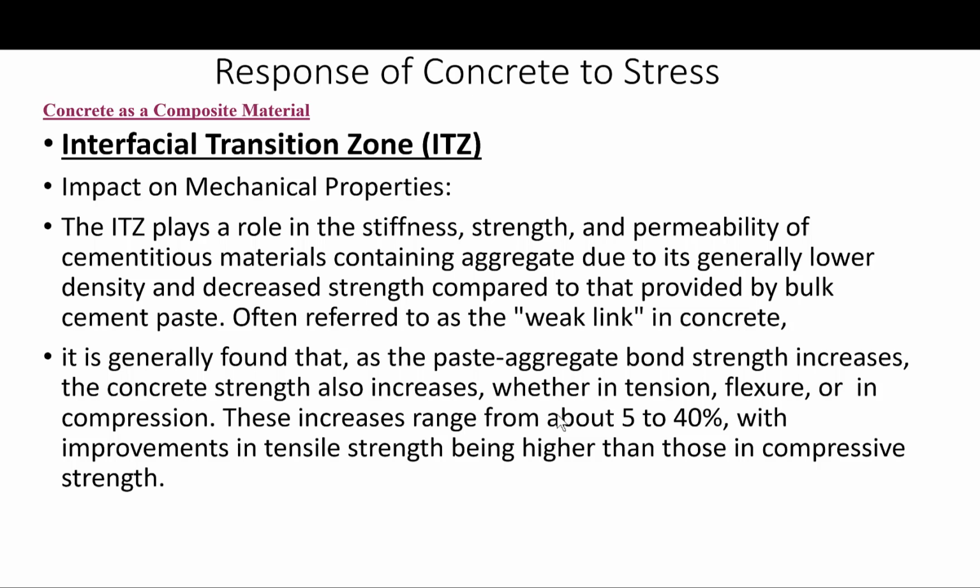So what we see are the effects of the ITZ on the mechanical properties. What are they? Currently, there are no standard test methods by which the strength of the ITZ, or more importantly, the bond strength between the aggregate particles and the ITZ, can be measured. There is no such thing.